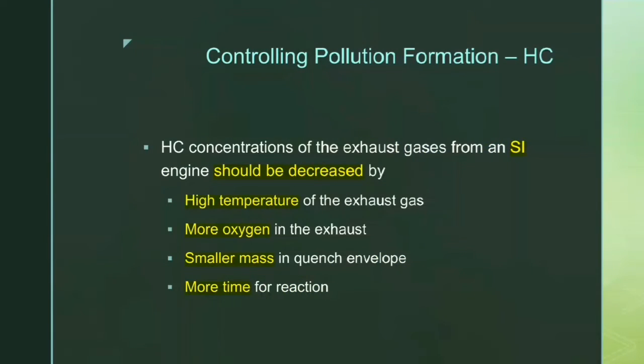Controlling pollution formation (hydrocarbon). Hydrocarbon concentrations of the exhaust gases from an SI engine should be decreased by high temperature of the exhaust gas, more oxygen in the exhaust, smaller mass in quench envelope, and more time for reaction.